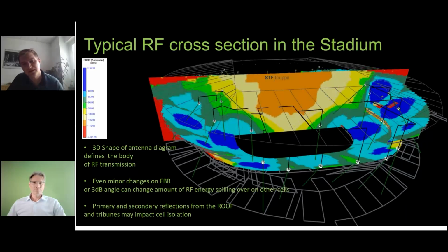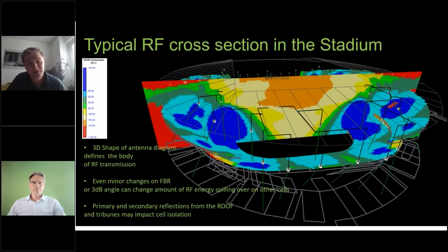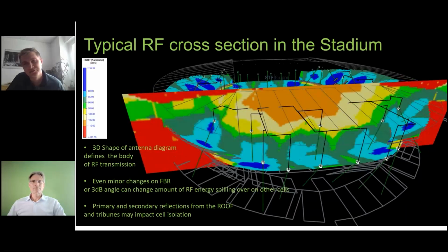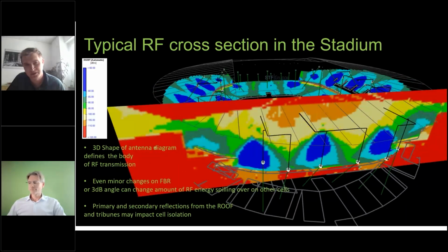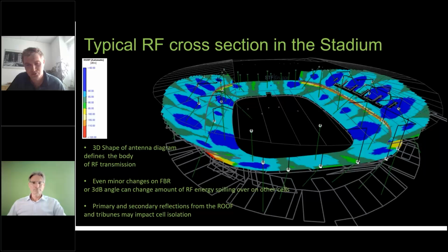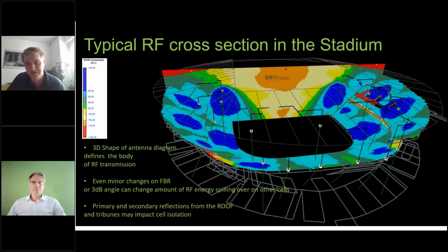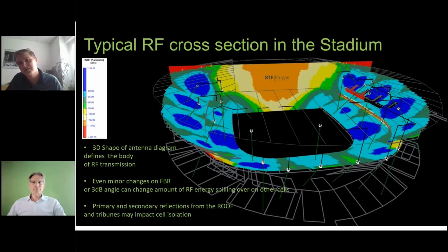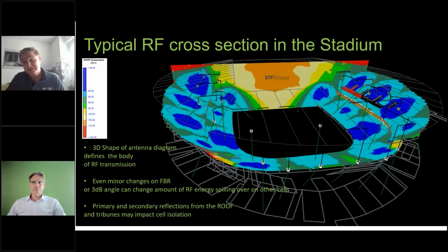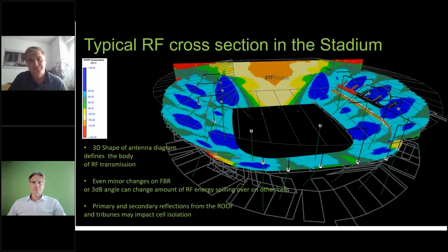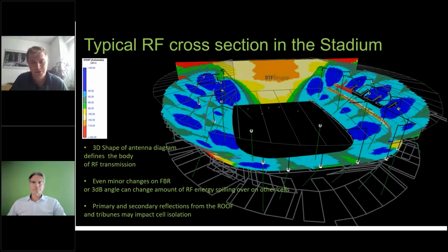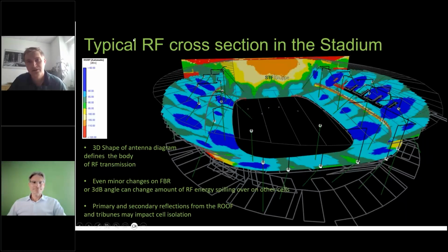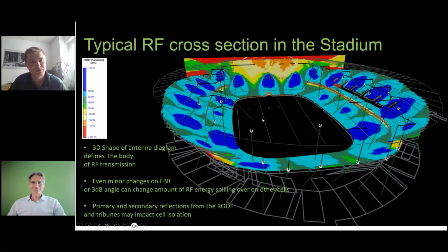And as I will try to explain, signal to noise ratio is the key metric and the key factor during network optimization. We always try to keep this SNR at maximum. As I said, when the network is overdimensioned, that maximum achievable SNR can be limited. When I say SNR, by the way, I'm mostly referring to PDCCH SNR. So I hope this picture is more or less clear for everyone who joined.